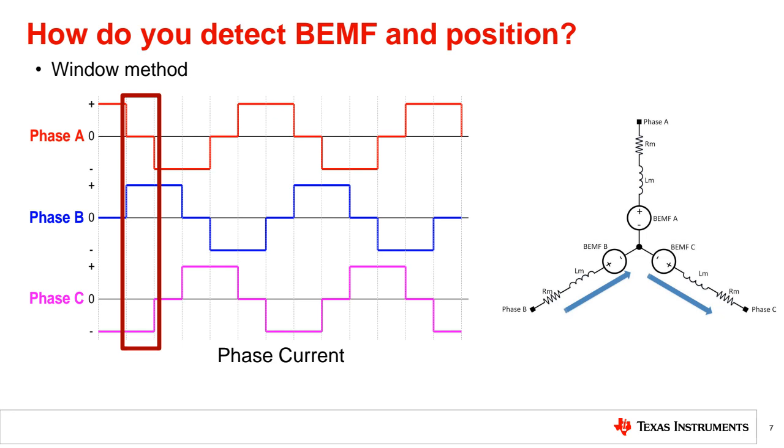Generally, all motor control applications use a microcontroller if you want high performance and high communication capability. Moreover, if you want to develop a sensorless control application, you must use a microcontroller. How can you read the current and voltage? You need to use the ADC module of your microcontroller. ADC means analog digital converter.